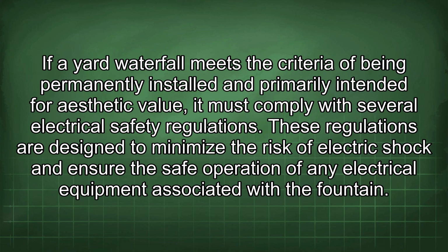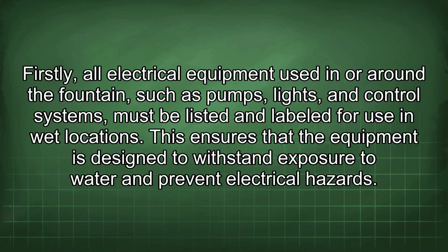These regulations are designed to minimize the risk of electric shock and ensure the safe operation of any electrical equipment associated with the fountain. Firstly, all electrical equipment used in or around the fountain, such as pumps, lights, and control systems, must be listed and labeled for use in wet locations. This ensures that the equipment is designed to withstand exposure to water and prevent electrical hazards.